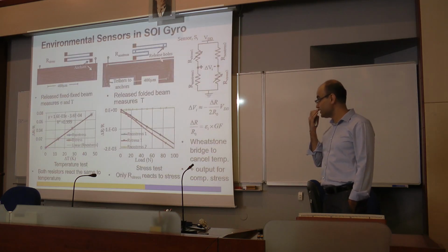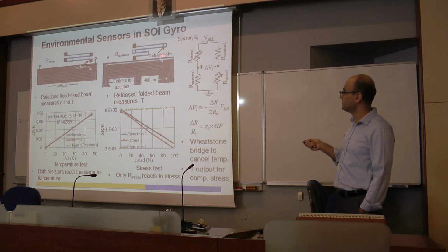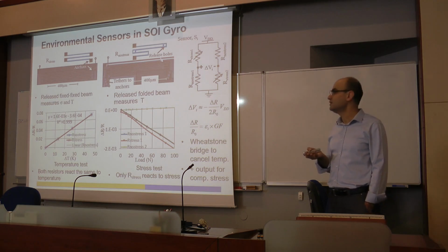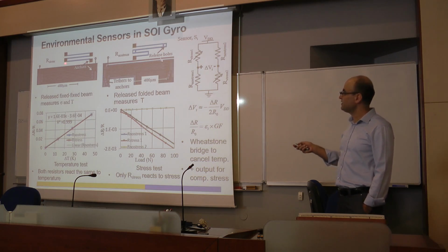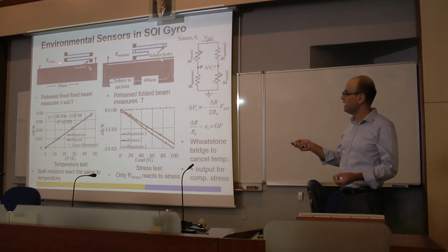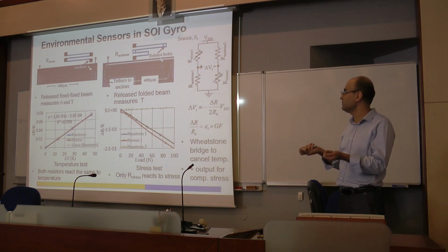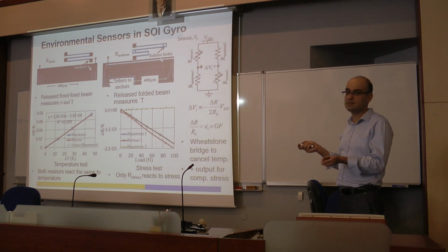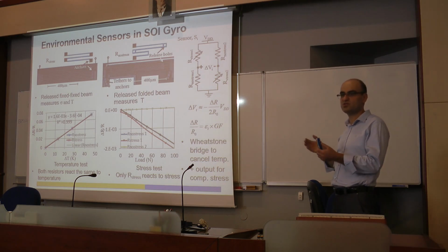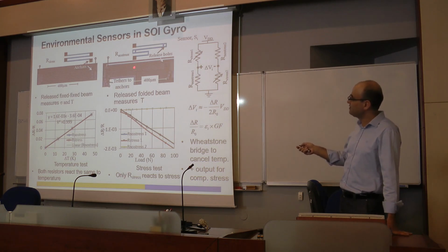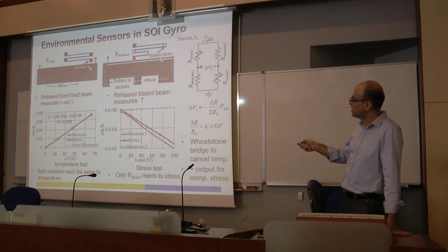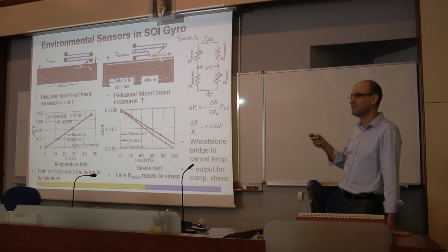So going into the real stress compensation results, these are the stress sensors that were designed. Silicon is piezoresistive. In other words, its resistance will change when we apply stress. So if you make a resistor like this, fixed from two ends, then whenever these two anchors displace, you'll have stress. But the problem is, this is also sensitive to temperature, because silicon has a temperature coefficient of resistance. In order to suppress it, there is another resistor. It has the same resistance, but it's just fixed from two ends, so there are no anchors. So this thing is not sensitive to stress, but sensitive to temperature.